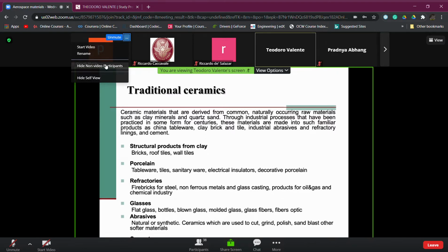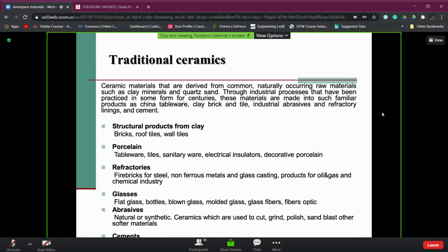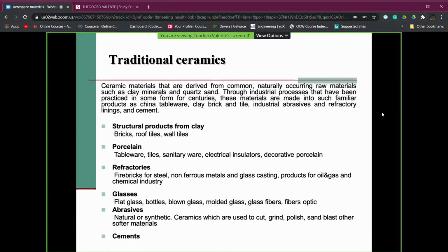a property which is going to make them different from the ceramic materials that can be interesting for us, which is the porosity. Because when we talk about traditional ceramics, usually we do have a level of internal porosity which can be sometimes higher, sometimes lower, but around 10%, which is a quantity not suitable for us when we want to discuss the possibility to use these materials as materials for structural components.